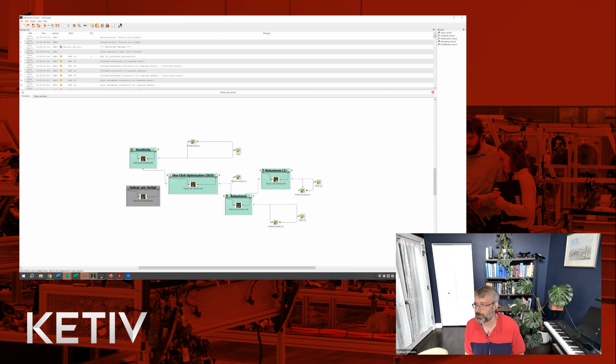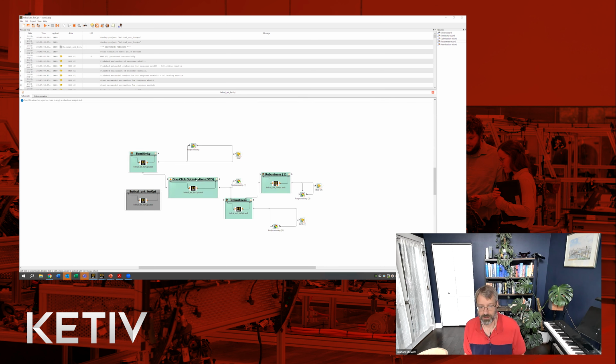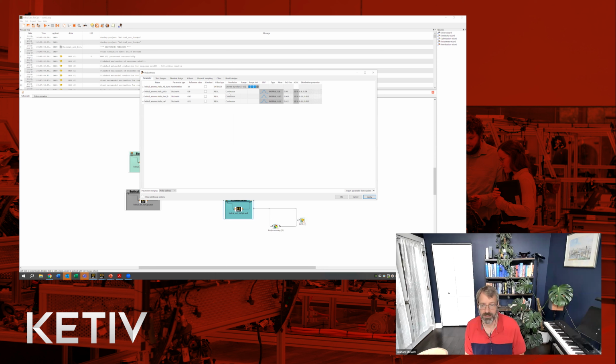And then similarly, and most importantly on the Monte Carlo side, we take a robustness wizard and drop it on top of the optimization, where it will then take the resultant optimized iteration from this analysis here and use that as a robustness, where in this case, we now have our parameters, and instead of our parameters varying by continuous variables, we now change them to stochastic variables here, where we can then indicate what the distribution is and how we want those variables to vary.